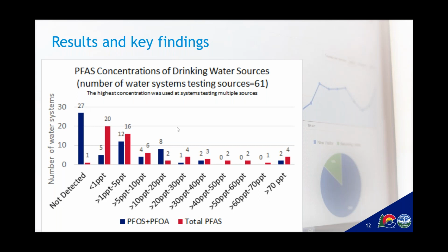And there were two additional systems of total PFAS above 70, and contacting them, they both use reverse osmosis just for other water quality issues. So, having that, their treated water looks a lot better for PFAS.